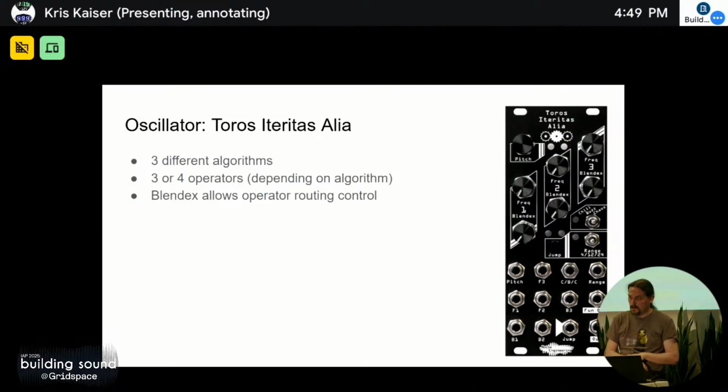So yeah. What is an all-pass filter? An all-pass filter is a filter that does not change the amplitude of any frequency. So you say 100 hertz, that is the point of 180 degrees phase shift. Obviously a circuit that doesn't modify the signal is an all-pass filter, but then a circuit that only affects phase is also an all-pass filter, which is usually the interesting thing. Those frequencies listed are where the 180 degree phase shift point is, and it essentially will, from 0 to max frequency, flip it all the way around.